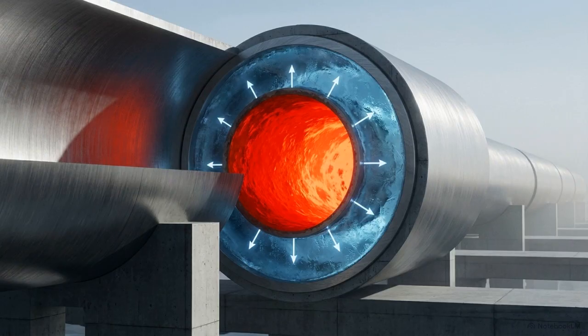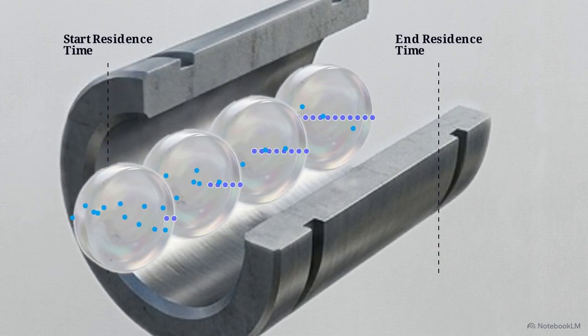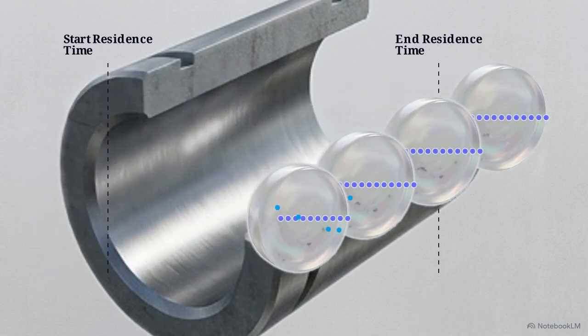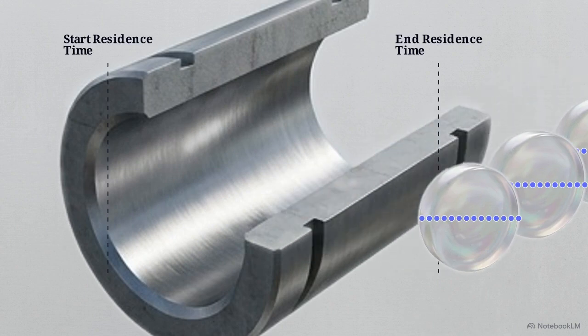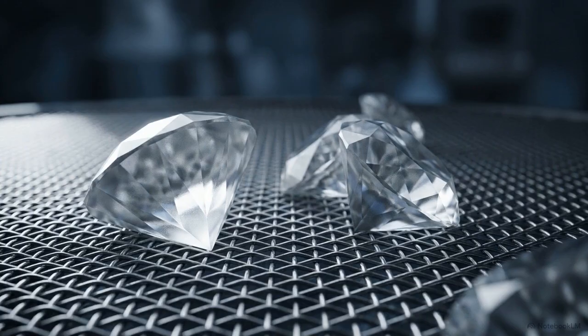Here, the continuous flow and superior heat management aggressively prevent the possibility of thermal runaway. In precise polymerization and esterification, the strict spatial control over residence time dictates the precise molecular length of the final polymer chains. Modern facilities are now engineering specialized PFRs explicitly designed to force continuous crystallization under strictly controlled flow conditions, overcoming the reactor's historical limitations with solid-forming chemistry.